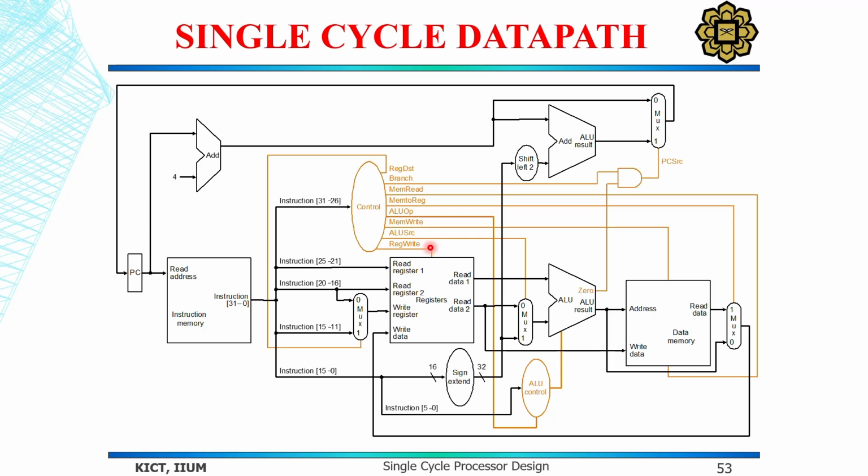So this we also discussed earlier, that we have 2 adders in the single cycle data path. Why 2 adders? Because in single cycle, everything happens in one cycle. So the ALU is busy doing the main operations like add, subtract, address calculation. So it cannot also compute the PC plus 4 at the same time. So we need a separate adder just for the PC increment, because we need to do everything in one cycle.